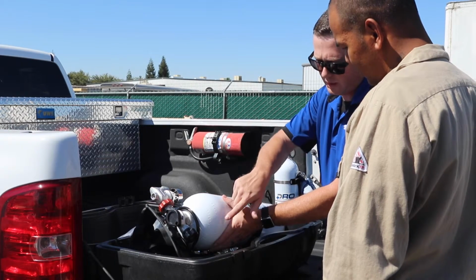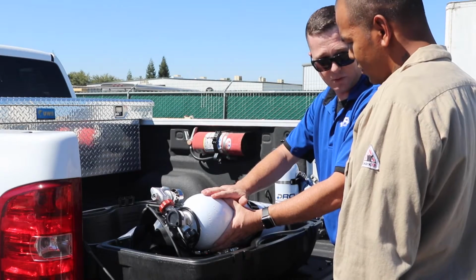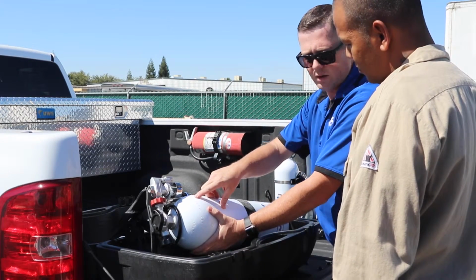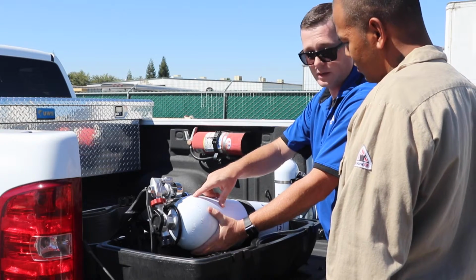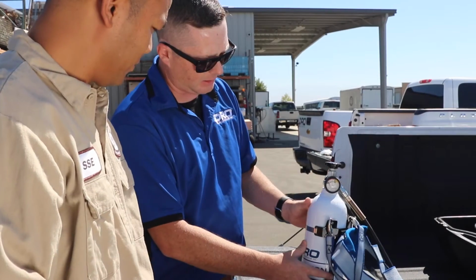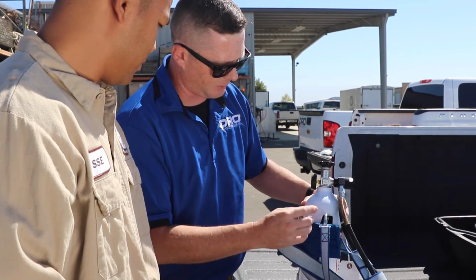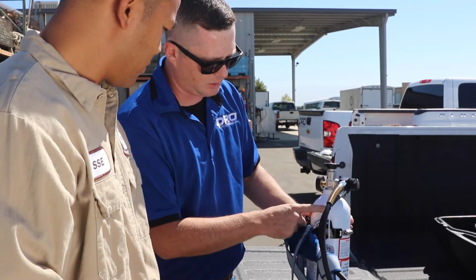It is important to note that just because the supplied air and equipment needed for work in IDLH atmospheres is supplied by a third-party company doesn't mean that you shouldn't inspect it for yourself. Compressed breathing air must meet at least the requirements for Type 1 Grade D breathing air. It should also be equipped with suitable inline air-purifying sorbent beds and filters. These requirements should be inspected by you before using any of this equipment.